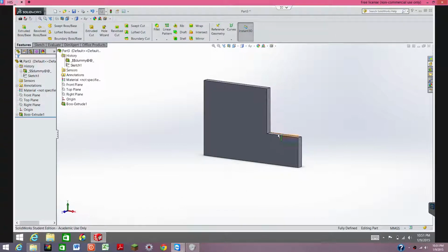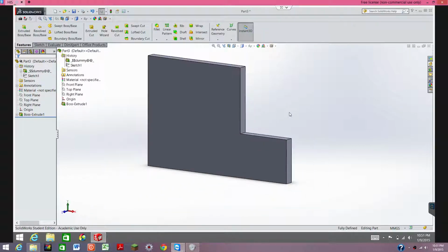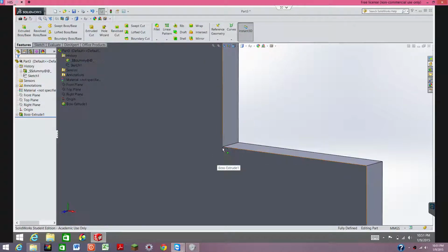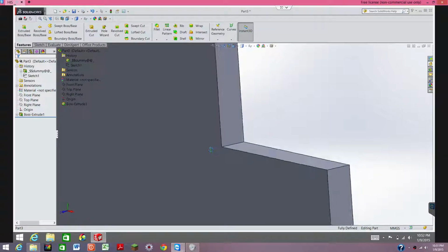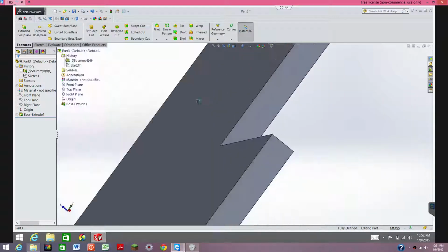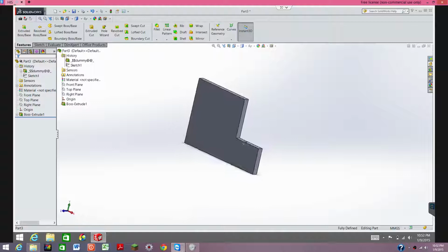Okay, now let's say you were doing an assembly. I just used the wheel mouse button again, but this time I rotated the wheel in and out to zoom in. Let's say you wanted to get in real close to this shape like you were doing an assembly, and you wanted to rotate around this part here, so you would wait till it turns to that point, click on the wheel mouse again, and that button will highlight and turn to this icon. Now when you rotate, it's going to rotate around that specific point in space, or orbit around it actually. And then we can also wheel mouse out again, and it's still rotating.